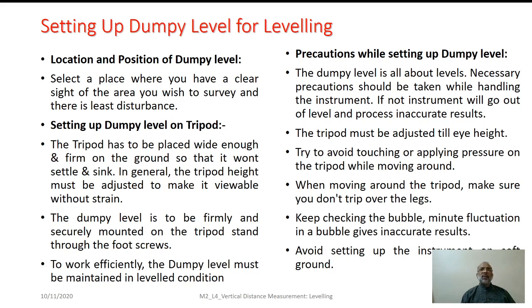Usage wise, we have to work strategically with the level. The first part is deciding the location or position of the level. Here one must see that the equipment will be stable, it can be established firmly, there won't be much disturbance, and it will establish large control over the area to be surveyed.